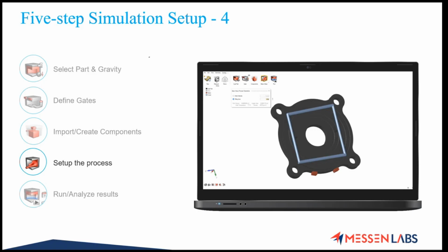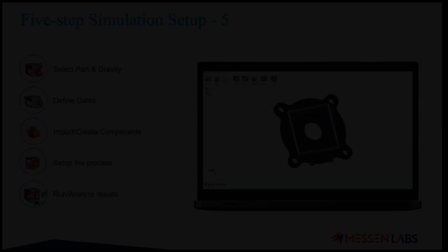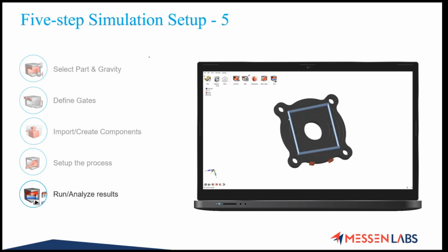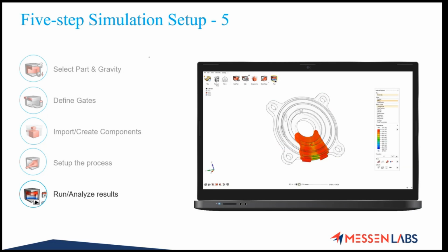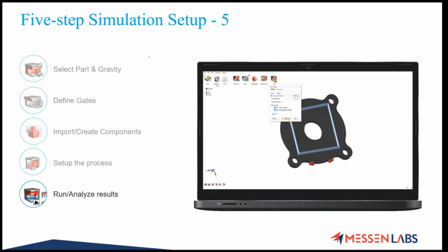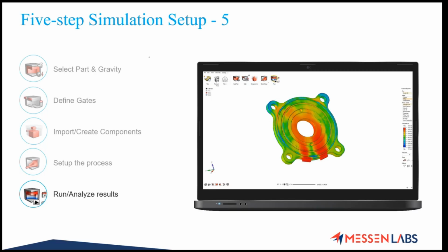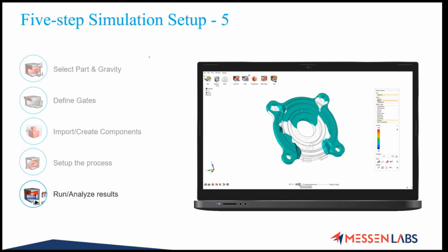Okay, once we set our model in the first step, we go for the setup process where we specify the casting process, which casting process we are utilizing, and by using the initial velocity or the final time, we can run the analysis. So finally, once we click on the run from the bottom, we can get different parameters as well as the results. Within a few minutes, the run will be completed and all the results like filling time, temperature, porosity will be available for you to test your simulation and the design of the model.